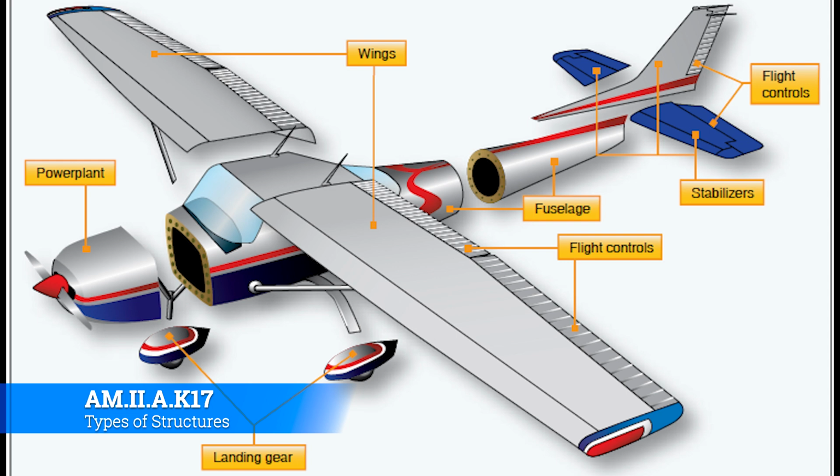All right, now there's a lot of different types of structures, especially the more complicated you get. You get up into some of the more mature heavy commercial aircraft, and you'll see all manner of different substructures and reinforcements to keep the wing skin from tearing in case of an accident or a depressurization event, things like that. But at the end of the day, the heart of a metal airplane is its semi-monocoque construction with all those parts and pieces that you should know.